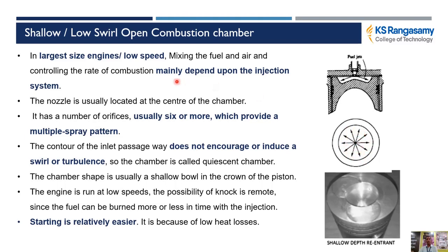So the combustion chamber mainly depends upon the injection system, not on the swirl system. But here there is a little bit of swirl inside the combustion chamber. That will not help the mixing of fuel with the air. So normally this kind of shape and design is used for large size engines and low speed running. If the engine size is large, the speed of the engine is low, because